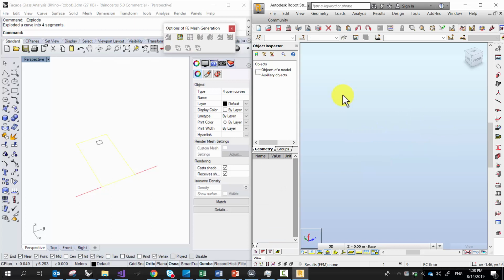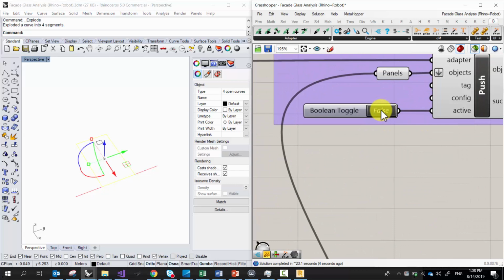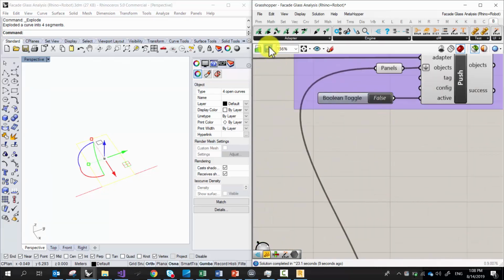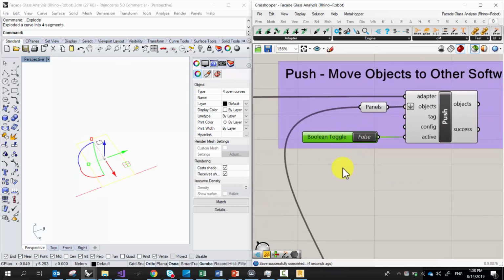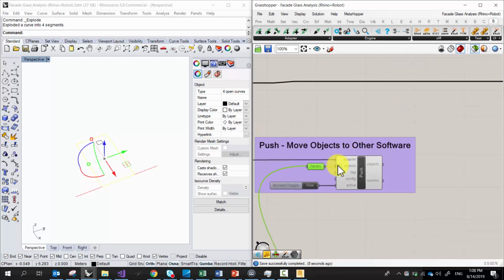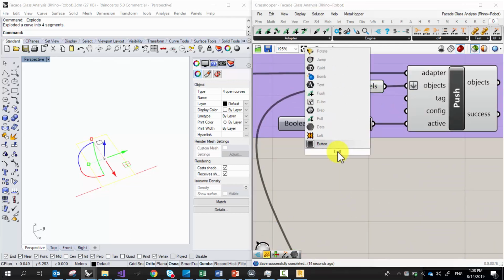So now every time I click, I'm waiting around for 5 seconds, 10 seconds, in this case 30 seconds, for stuff that doesn't mean anything to go to robot, okay? So be careful. I just put up a post yesterday on Yammer that says, hey, listen, just because you're working computationally doesn't mean that you're working intelligently. So we better save robot file separately? I'm not saying save robot file. If you keep this toggle on, then every time you make a change, it'll keep trying to run it, right? So in general, a good habit is to use something called a button.